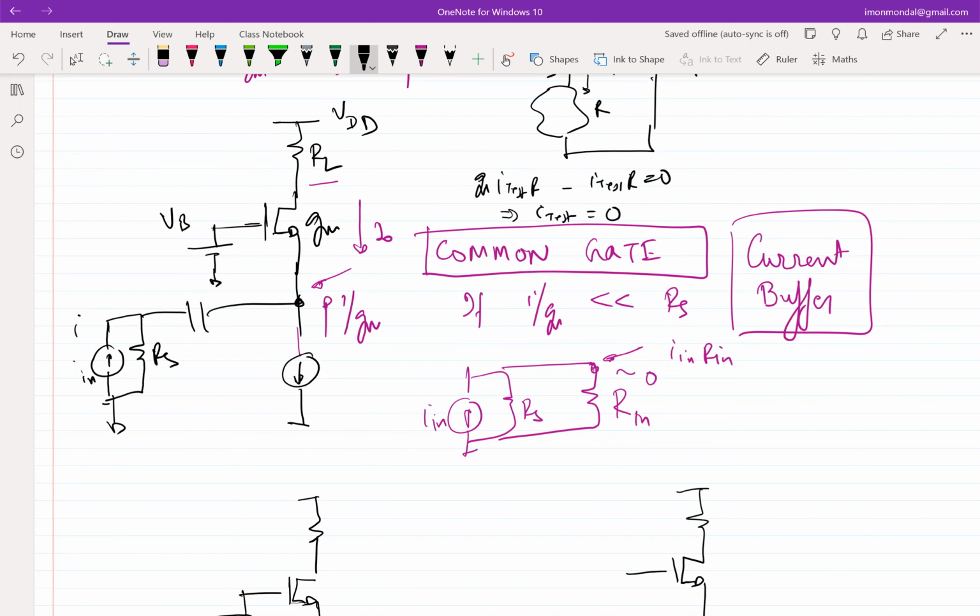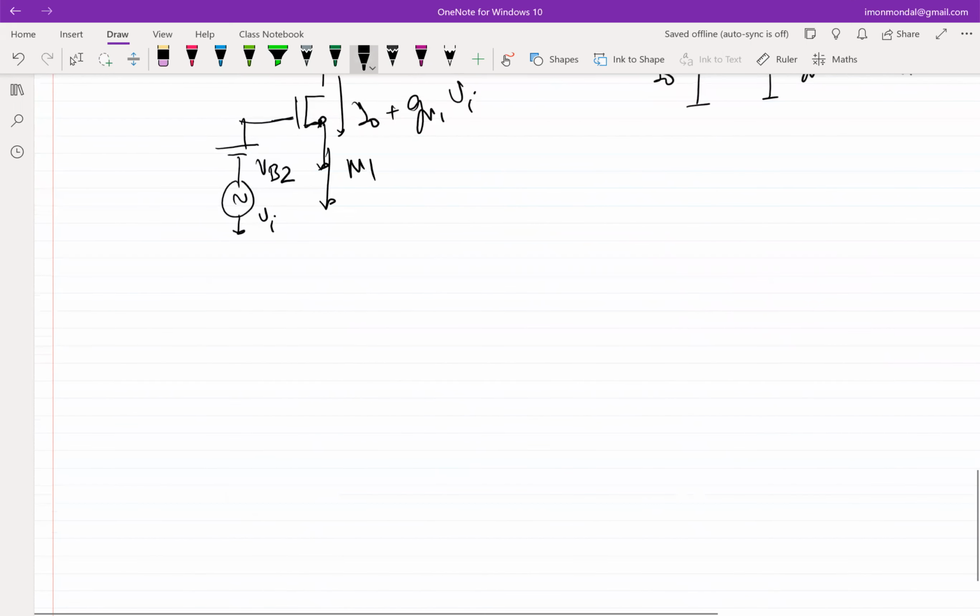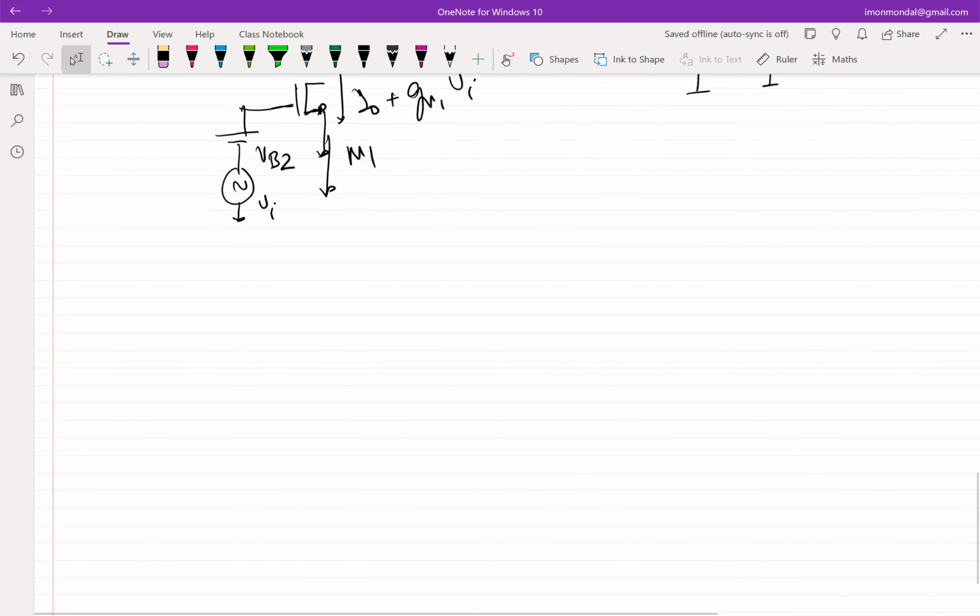Okay, fine. So before we end, by now you must be aware, or if you are not aware, this must be bothering you: how can a real transistor have an infinite output impedance? Nothing in reality is zero or infinity. You always model something; we model something as zero, we model something as infinity. They are flip sides of the same coin. In fact, the transistor output impedance incrementally is not infinity. It's a large value. Again, large is a relative term, but it's certainly not infinity.